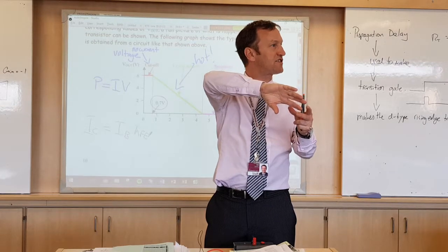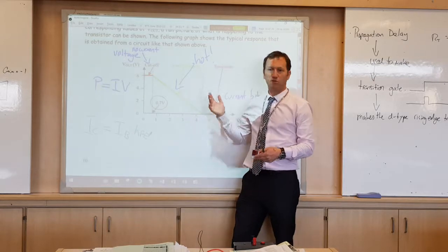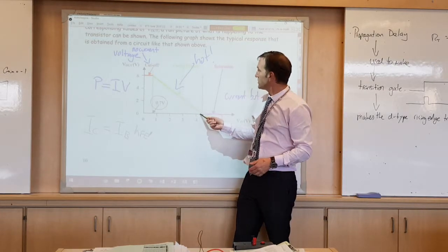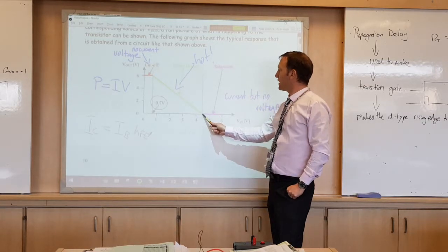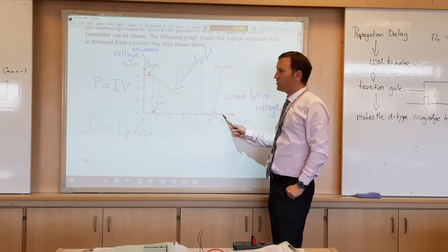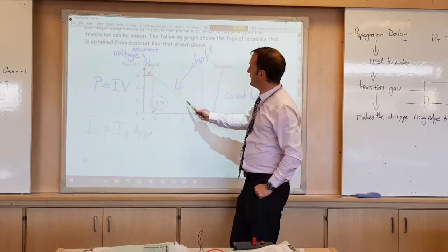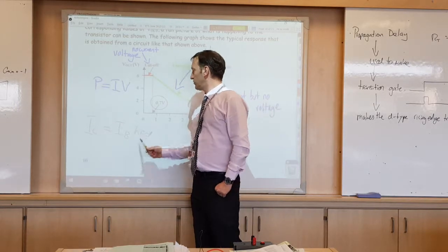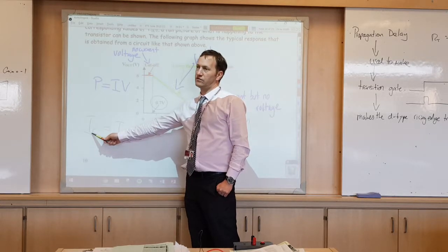It's like it's saturated. A transistor's the same. You can't have a transistor more open, more conducting, than fully on, because its resistance is practically 0. So that's where it hits this point here, the saturation voltage, and after that point there's no linear relationship between IC and IB. So this bit here, the linear region, is where this holds. We can multiply the base current by HFE to find the collector current.